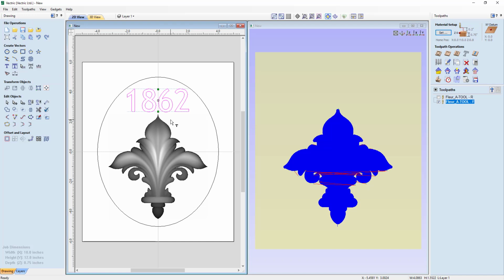then my text bounding box will now have two green handles and then the center handle that I can use to drag it around with. So if I left click on this top green handle, I can pull it up. If I put it back in its straight position, I can use the bottom handle and I can pull it down. So that's pretty neat. So let's just go ahead and angle it up. And what I'm looking for is the top of those letters to be a little bit equal outside of my ellipse. That looks pretty good right there.